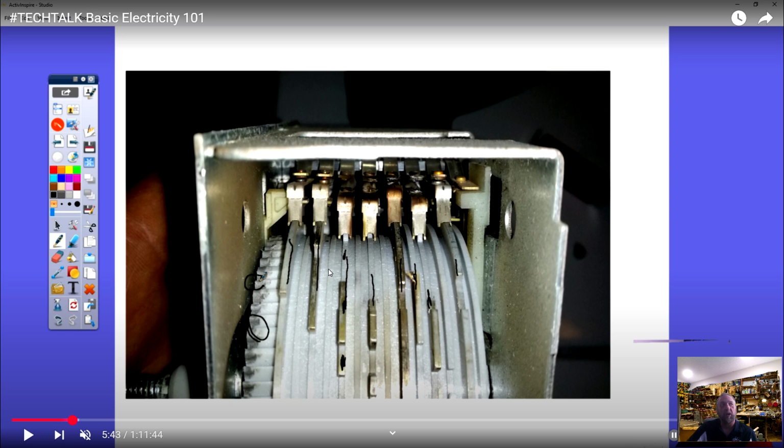So these switches aren't running like you see a machine constantly moving. These switches slowly click, 2 minutes later, click, 2 minutes later, click, and that's what's happening. Now, if you look, some of the points of these switches look pretty burnt. This machine's timer had its fill, but some of these others are nice and clean. These get used more often, and that's how a switch fails. Every time a switch opens and closes, you get arc heat and it burns.